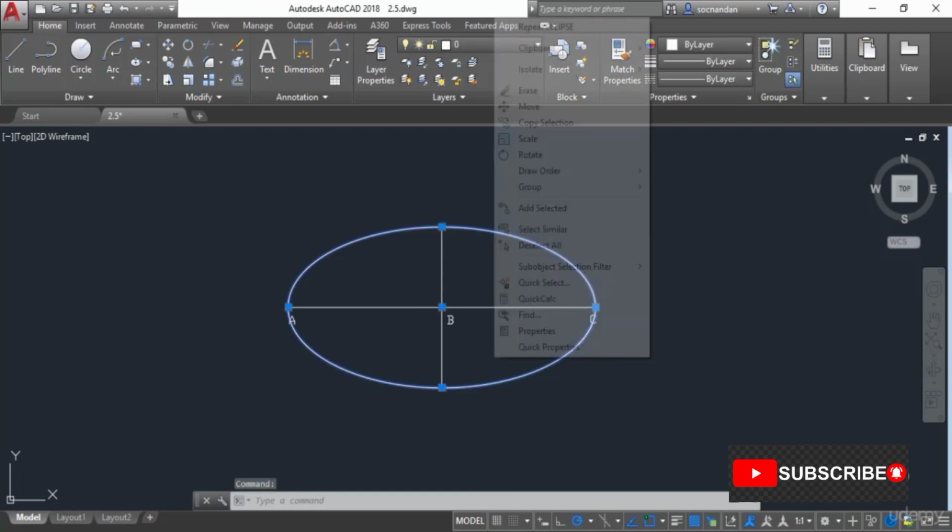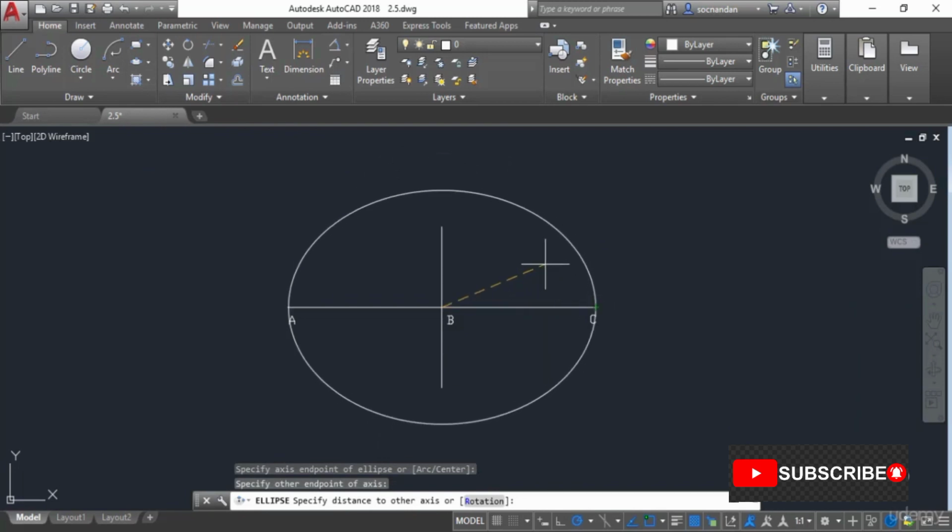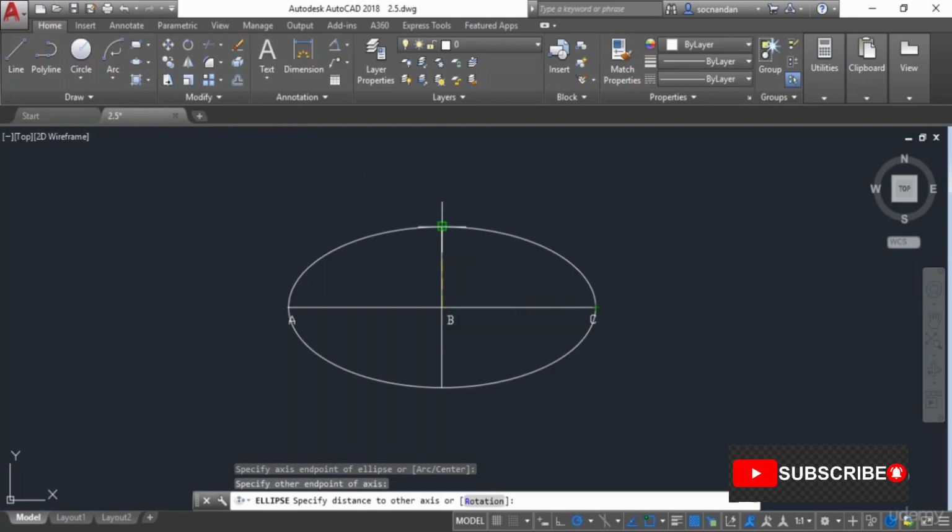So now let's erase this ellipse and let's select the second method, which is axis end. Now in this case we need to specify the 2 endpoints of the axis. So I'll select the A point as the first axis endpoint, and then point C as the second axis endpoint. And now we need to again specify the endpoint of another axis. So here in this case I am again selecting this point, and here we have it. So the only difference between these 2 ellipses is, in the first case we need to specify the center and then the endpoint, but in the second case we have to specify the 2 endpoints.